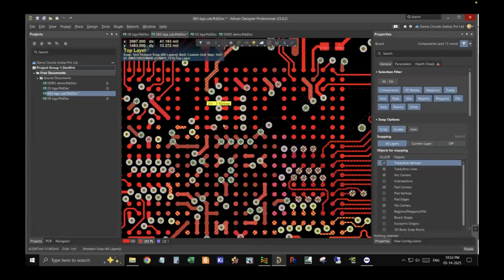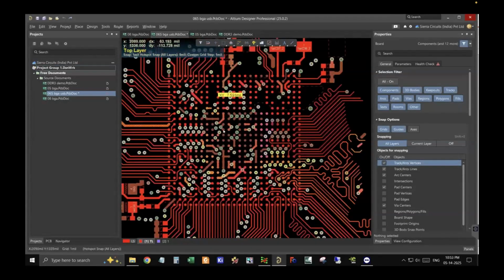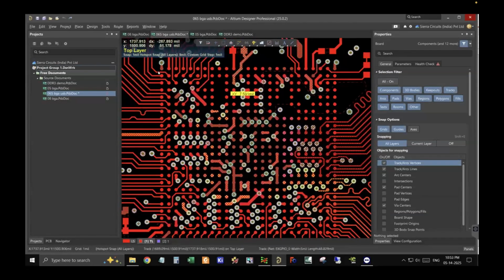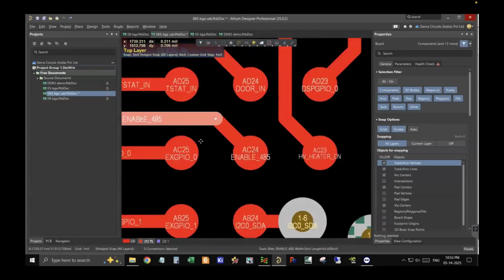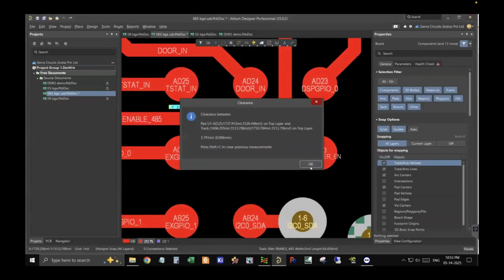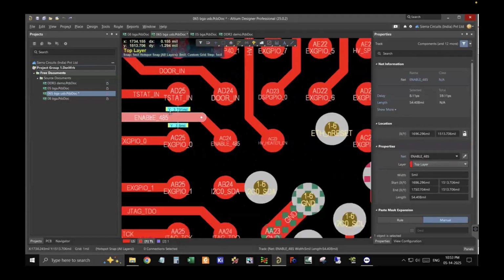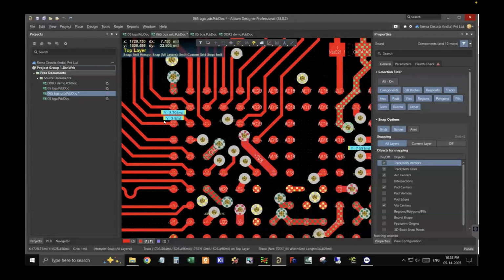So again, the same thing we have followed. We have tried to route all the traces on the outer layer. I'll just show you the trace fit. Here it is 5 mil, and the air gap here is 3.79 mil, which is slightly less because the spacing is less in this case. But 3.79 mil or 3.8 mils should work perfectly fine with your quarter ounce copper foil on your external layers. So this is when it comes to the 0.65 mm pitch BGA.